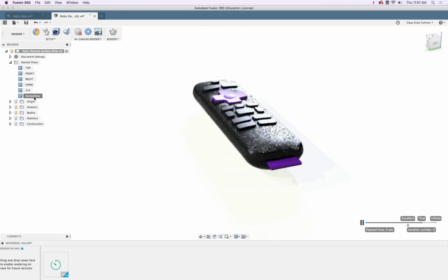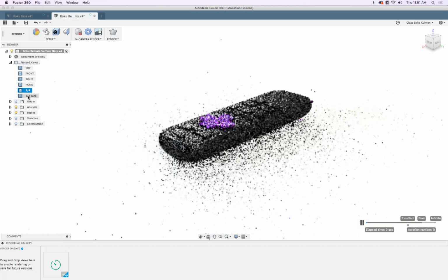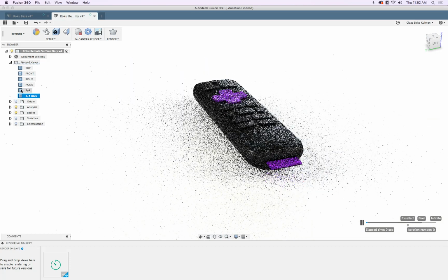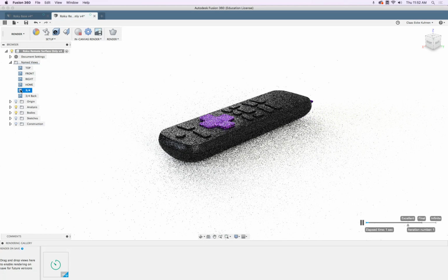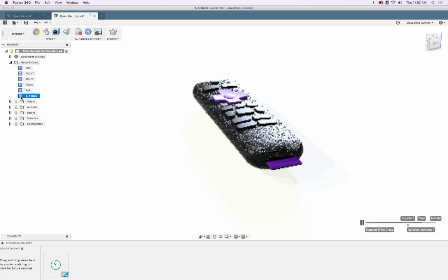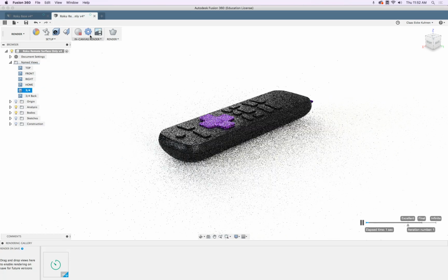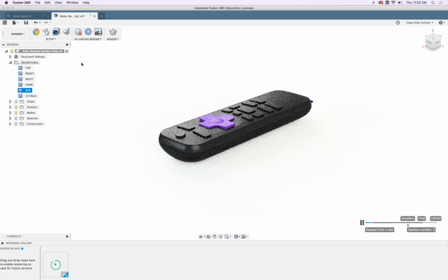Whoops, should have double clicked this one. 3/4 back, and you see it there. This way we can position, specify particular views from where we look into the scene, and then when we have to re-render something, we don't have to try to find that position. We simply click on that view, and then we hit render and create a new image. And that, in a nutshell, is pretty much everything about how to set up the rendering.